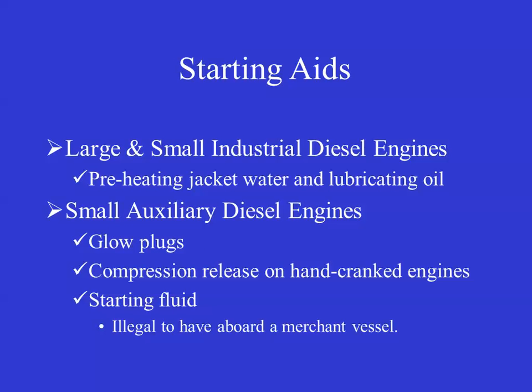All right, so again, in large and small industrial diesel engines, you're usually preheating your jacket water and lube oil. In some cases with small auxiliary diesels, you may have a glow plug, and we'll show that in a minute. Compression release I just mentioned on the hand crank engines. And you can also use starting fluid. Starting fluid is typically ether. It can be purchased at any automotive store. It's commonly used by farmers to start their diesel tractors out in the field.